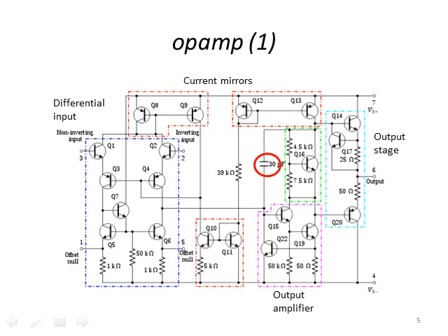We have current mirrors in this structure to help set up the bias currents, that help set up the operation, to make sure that the operational amplifier is operating in a linear region. And then because this does amplification, we have output amplifiers in an output stage that basically allows you to source higher currents so that it doesn't affect the frequency response of the system.